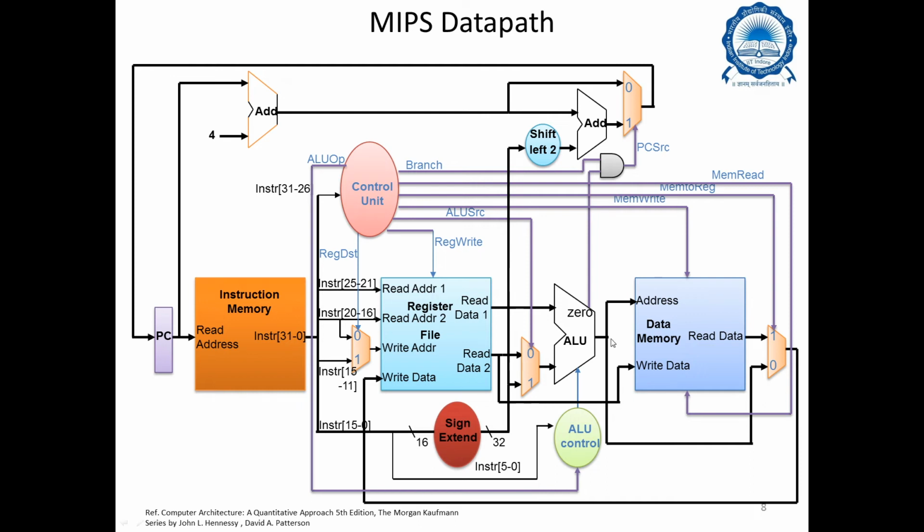So that is another possibility here. Therefore we have a bypassing of this unit totally, and this gets connected to this multiplexer, while the other input of the multiplexer could be the read data of the data memory, which is the data that we want to load from memory in case of LW. Okay, so therefore we have two different types of inputs here in case of this multiplexer.